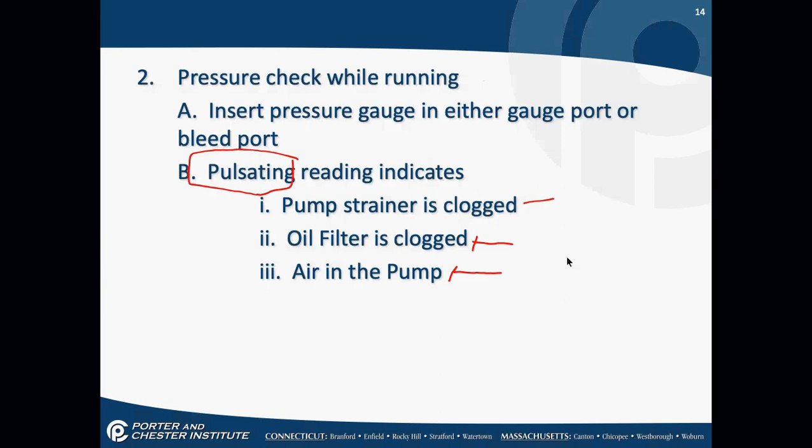It's actually pretty easy to troubleshoot an oil burner. 9 out of 10 times problems with oil equipment on the mechanical side is air. There's air in the system someplace. Fittings wear out over time. Gaskets wear out over time. Something is letting air into a system. And just because there's oil in a line, the oil may not be leaking out. It might just be allowing air in.